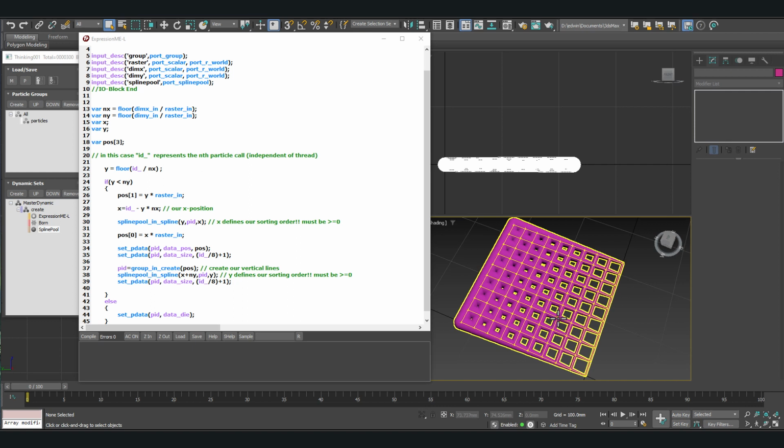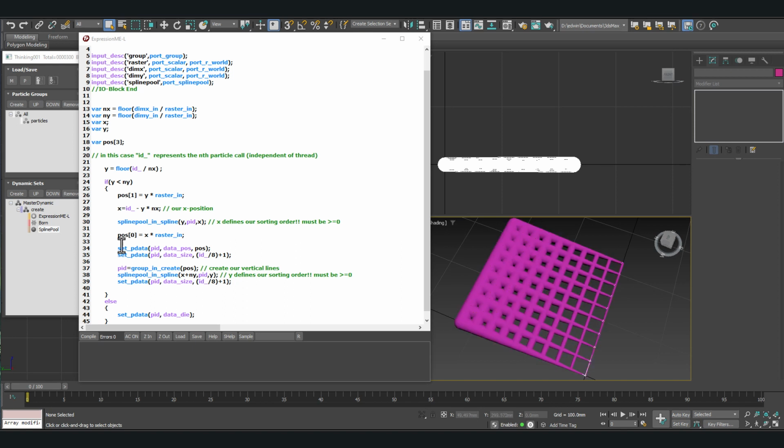By the way, thinkingParticles 7.3 comes with a lot of sample files. In total, we have over 400 sample files. We have a lot of sample files for MEL alone, including this scene you saw here. So you can recreate this scene, go along with the video here. Just download these raster spline scene, or you don't need to download it, it's automatically installed. Just load the scene and walk it through and try some things. Click into the code you want to explore, into the variables you want to explore, press the help button, and you get the information and know how to use it.